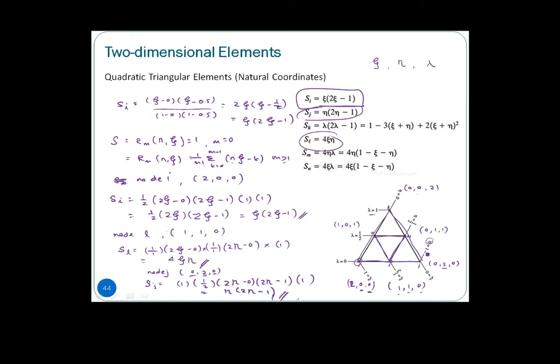Then we also have the mid-side nodes or midpoint nodes, which are L, M, and N. First, basically it represents the order in terms of layers, right? If you are looking into the coordinate itself, for I it is when psi equals 1. You see or not? This is when psi equals 1, so the rest, lambda and also eta, are 0 in this case. So it's 1, 0, 0.